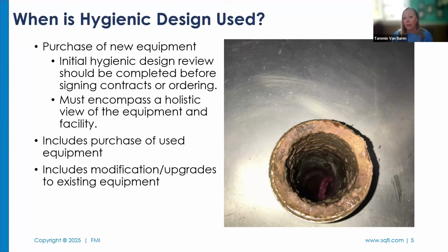Our failure was we didn't do the hygienic design up front. We waited till it got to our building and then tried to figure out how to clean it. And it was just not possible. As you said, the welds weren't smooth, and there were threaded fasteners that were exposed, hollow legs.